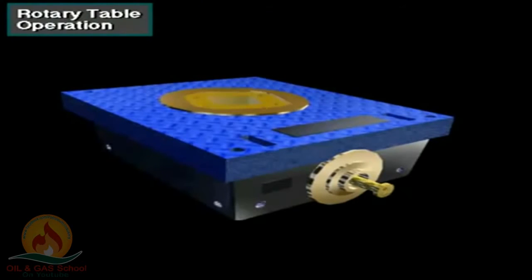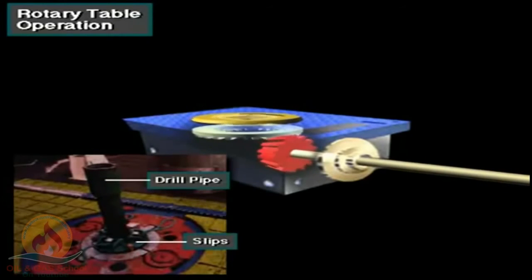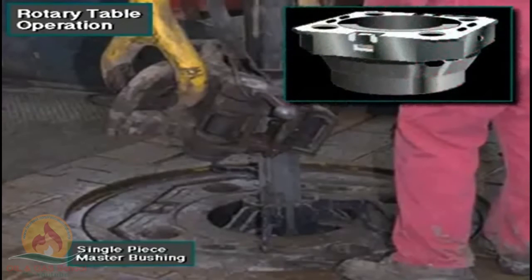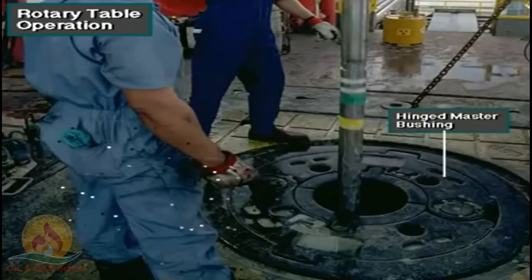The rotary table performs 2 functions. First, it transmits rotary motion to the master bushing, which drives the Kelly and drill string. And, with assistance from slips, hangs the drill string. The master bushing goes inside an opening in the rotary table. Small master bushings are usually a solid single piece, as shown here. Large master bushings are either split or hinged.